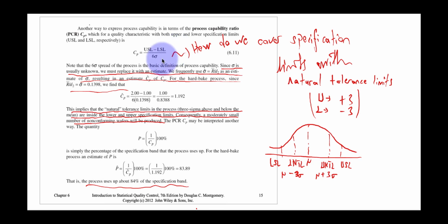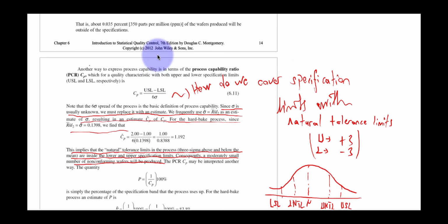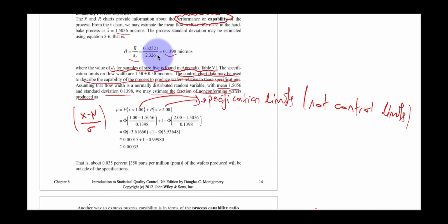So we said we are going to estimate process capability, because in the true process capability we use the true standard deviation value, but mostly we do not know the true standard deviation value. We can estimate the standard deviation by our formula, right? What is our formula?